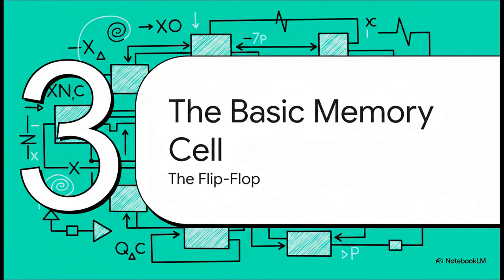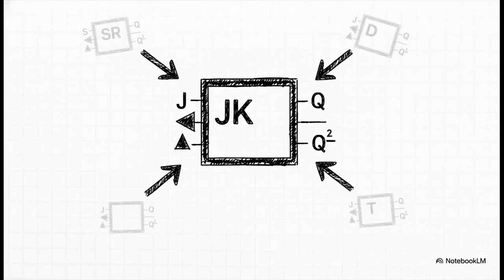Okay, so let's zoom in a bit. Let's study this fundamental 1-bit memory element in more detail. This element is the flip-flop, and it truly is the basic building block for pretty much all sequential logic. Now, in your course, you'll come across several types of flip-flops. There's the SR, the D, the T, and the JK flip-flop. For our discussion today, we're going to focus on the JK flip-flop. And why is that? Well, it's because it's considered the most versatile of them all. You can actually make it behave like any of the other types.